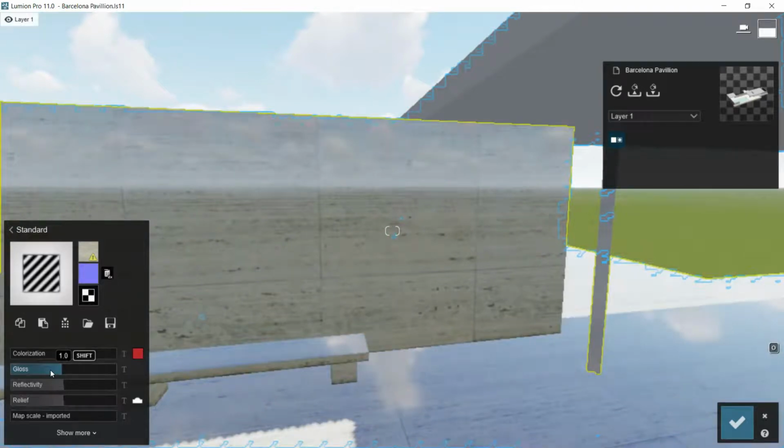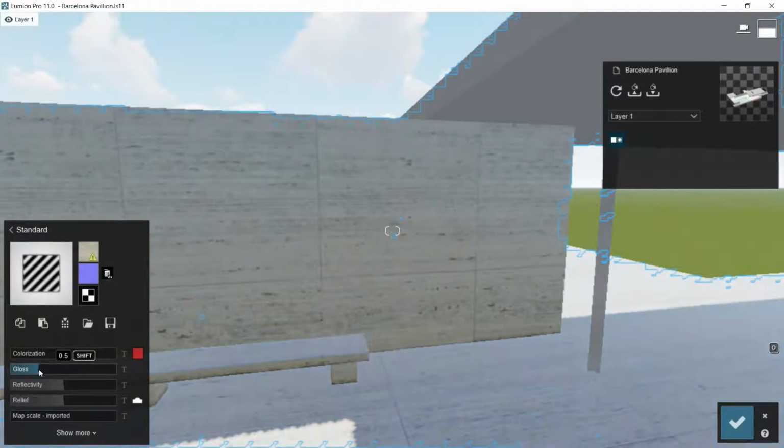You have to take into account that when we are editing a material, and I mean a standard material, here in this option, standard, all the values of the slide bars are going to start at 1.0. These are like neutral values. So we have to adjust these characteristics of the materials to our stone, to our metal, to our wood, whatever. Here, this stone clearly does not have that brightness, so we should go with a value under 1.0 at gloss. Let's say 0.4, for example.